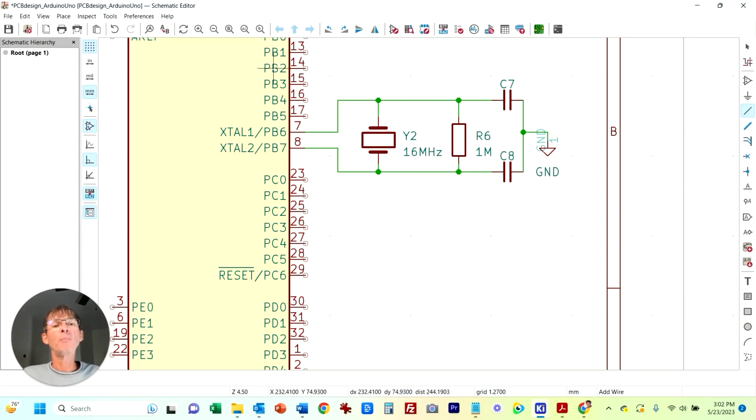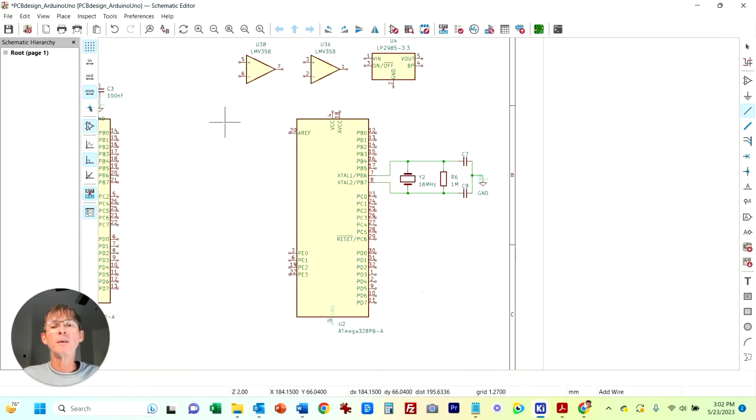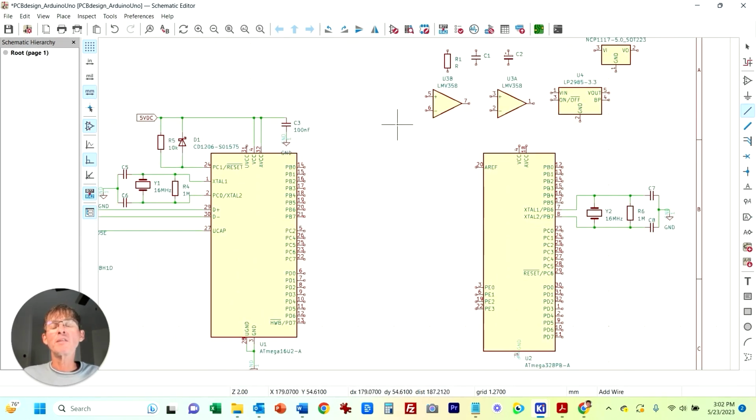get into this when we start to do the PCB layout. This is one of the circuits that's kind of critical in regards to how things are placed. Most of the layout on a board like this isn't really that critical. It's typically the things that have the most complexity when it comes to designing the custom board are anything that has really fast switching.